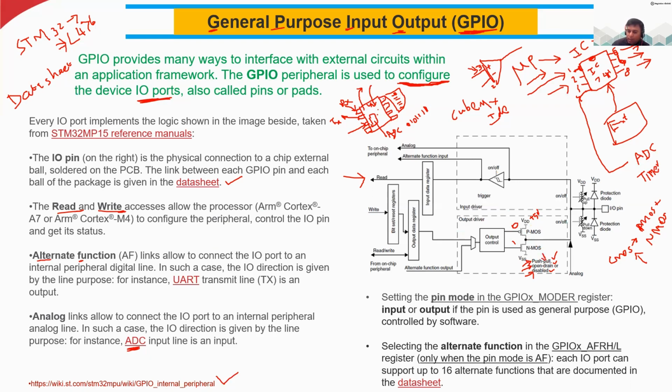This is possible in the user interface. In the graphical tool, either CubeMX or IDE, you will see these options. But generally, we keep this as push-pull mode. This is the default mode we are keeping. Okay, this is about GPIO. I think you can read these two more things. I always suggest you read the data sheet. That is the one having all the detail about your microcontroller.